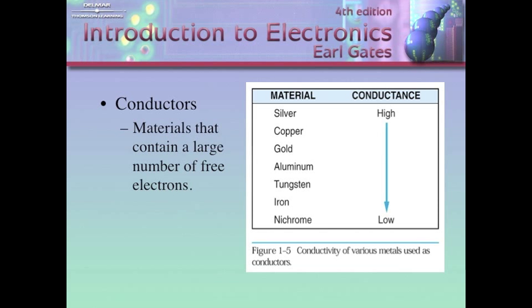But gold doesn't tarnish. So that's the reason that we use gold plating. One of the most popular conductors that we use is gold-plated copper wiring. So if you put that gold plating on it, it won't oxidize. And then if you're putting a male-female connector together that are both gold-plated, they're clean. They're not oxidized. You put them together, you get an excellent electrical connection.